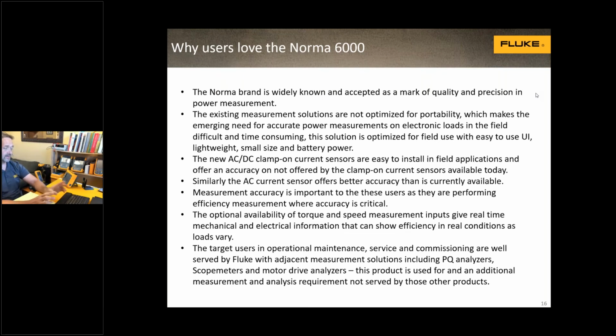So you can get your real-time mechanical and electrical information, so you can measure real-time efficiency of the motor while it's actually in operation, but also use NEMA as a possible guideline into seeing how the motor is operating and its characteristics and make adjustments if necessary.